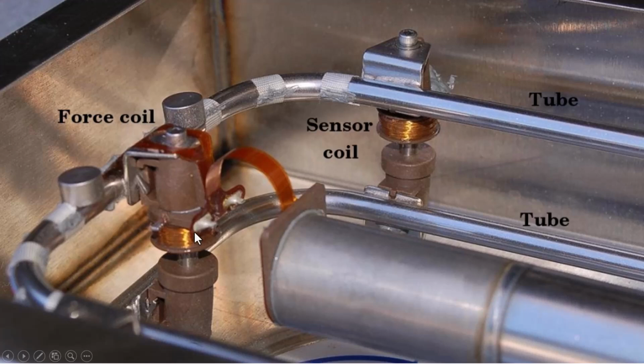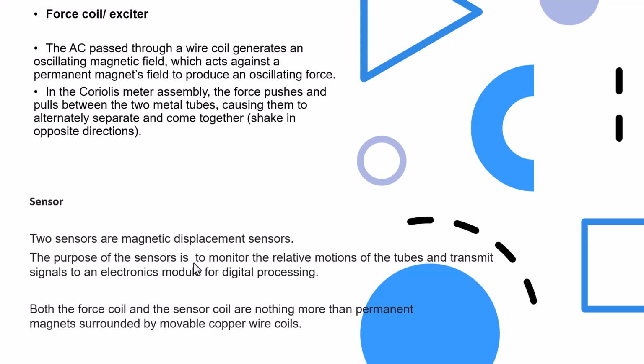This one is the force coil connection. AC power creates vibration, so it makes the tube vibrate. The AC passes through a wire coil and generates an alternating magnetic field, which acts against a permanent magnetic field to produce an alternating force. That's important.